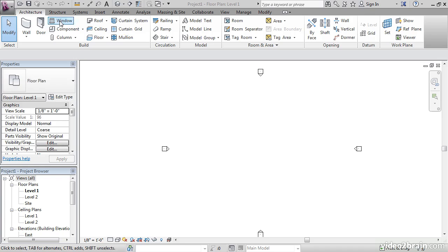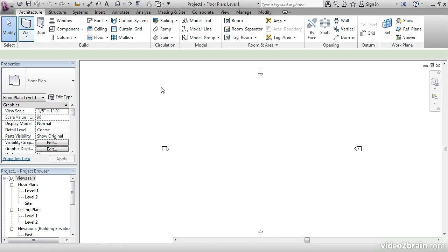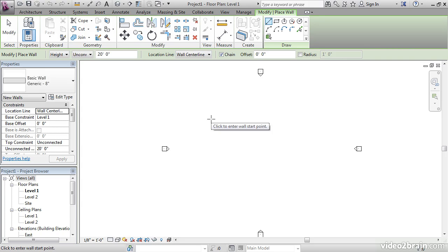At the top of the Revit window, you'll see a series of little buttons, or what we call tabs. Each tab contains the icons that you will use. These icons are sorted into what's called a panel. So you'll hear me say, on the Architecture tab, click the Wall button on the Build panel. Let's actually go ahead and do that. Go ahead and click the Wall button. In Revit, once you start a command, the interface will change to give you tools to aid in that command. Another thing that Revit adds is called the Options bar. You'll be hearing me say this throughout the course: keep your eyes on the Options bar.